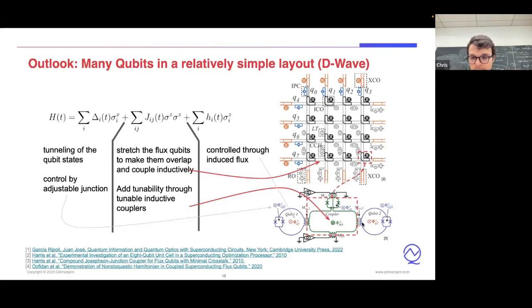And these are the subsystem of two flux qubits. And if you want to have more, then in the scheme of D-Wave you can just extend the wires of the qubits such that they overlap with, I think, 8 qubits in this drawing. So these qubits can interact with each other, and this interaction can be controlled by this coupling circuit, which sits at the crossing of these qubits. So in this scheme, you can already understand the basics of the annealing layout.